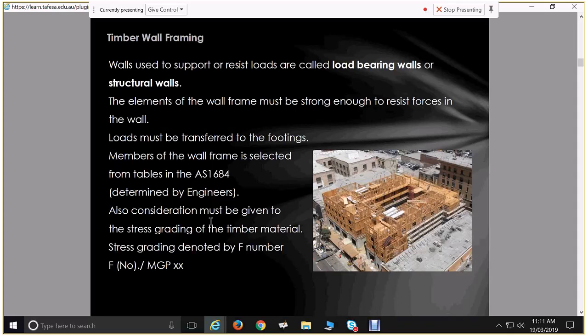Yeah, I don't know the intricacies of that and why we don't have machine grading for the various different timbers, but it might also be just a thing of commonality. So much of our timber is pine. We have a lot of pine which is grown in places like Mount Gambier, and that's what we use primarily for building, so much of it is pine. For flooring, that is just visually graded. Yes, so you've got visual gradings for flooring as well. So you've got both hardness and stress that you have to consider. You also have to consider what things look like as well.